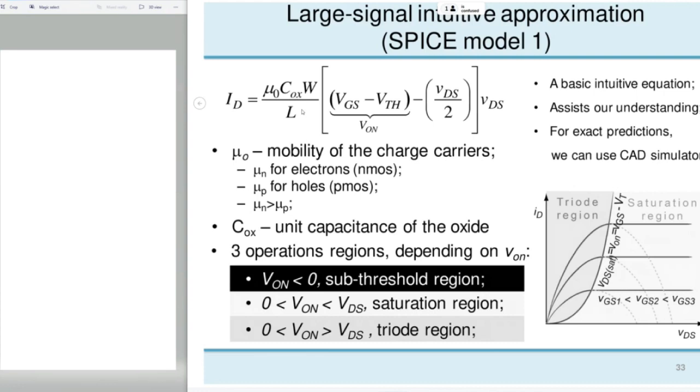So often in jargon among engineers, we say PMOS transistors are slower. They're not fundamentally slower because the mobility of the holes is lower, but they're slower because they have more parasitic capacitance, and more parasitic capacitance means that the time constants are longer. This means that charging and discharging the nodes around the PMOS transistors usually takes a little bit more time than for NMOS transistors.